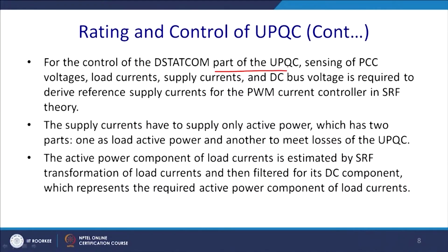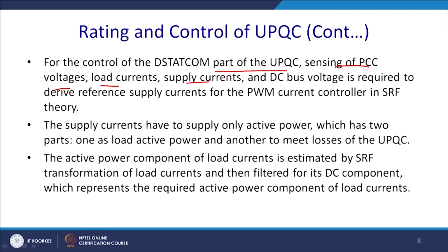For the control of the D-STATCOM part of the UPQC, these are the sensors you require: sensing of the PCC voltage, load current, supply current, and the DC voltage, to find out the reference of supply current for the PWM control according to the SRF or instantaneous reactive power theory or whatever may be, mostly in the time domain.